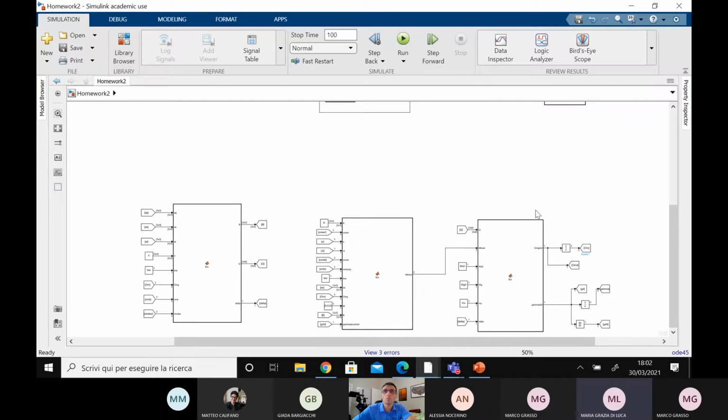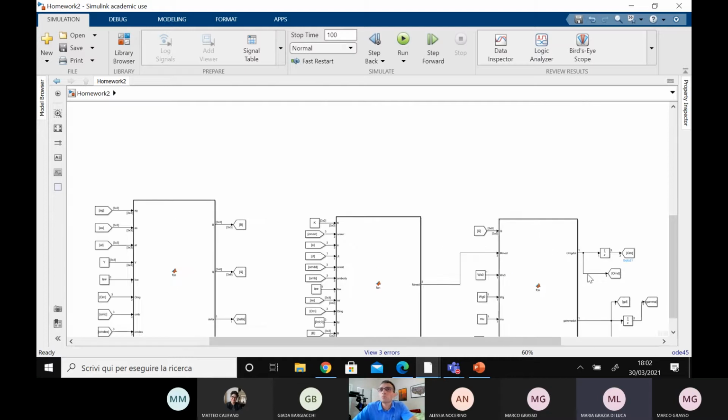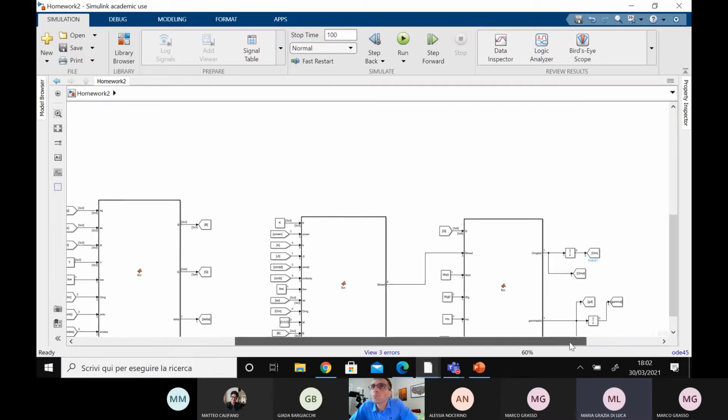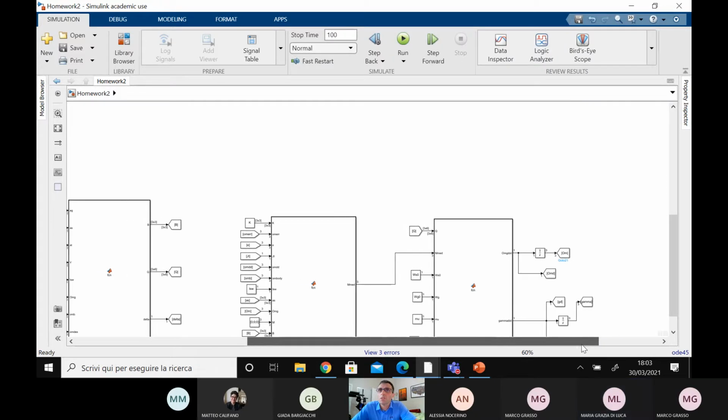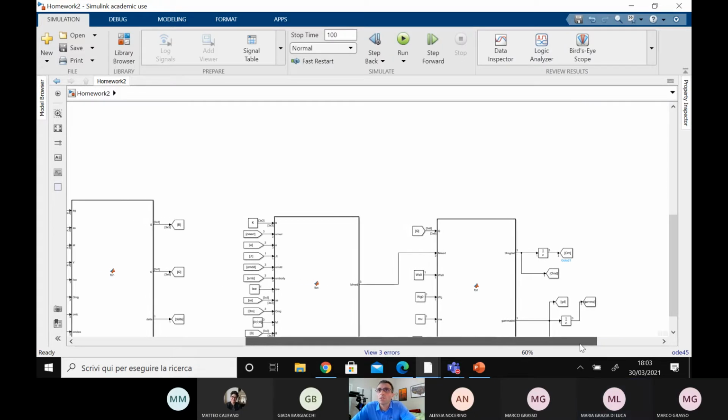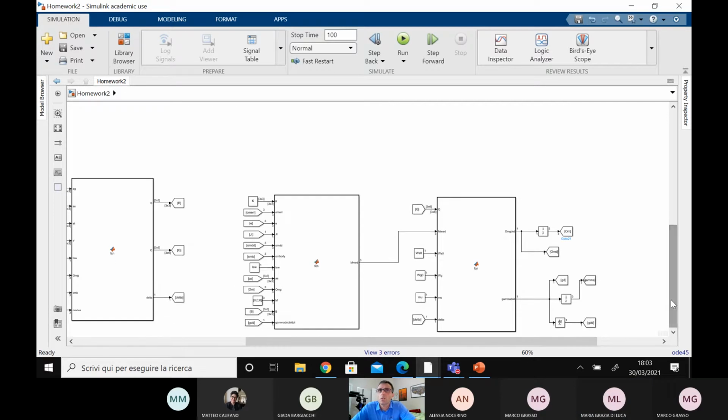Okay, so it was working if I used gamma dot and omega dot as the constant, as I had it before, and it's not working now. So I was trying to understand what happened when I defined this. It seems like the dimensions of what's coming out do not match. It understands that your initial conditions for the numerical integrators are dimension 3, but what's coming out of the block says it's 1.